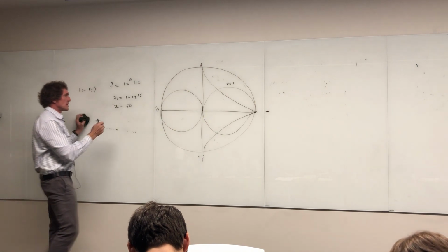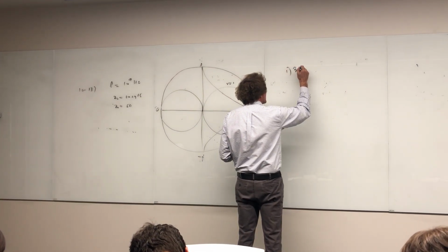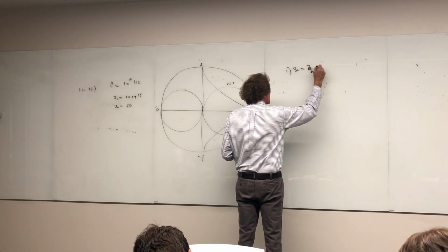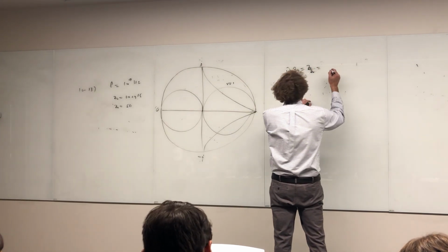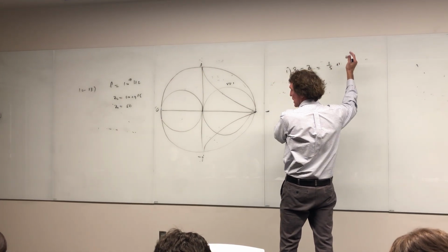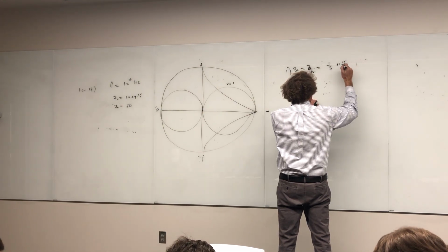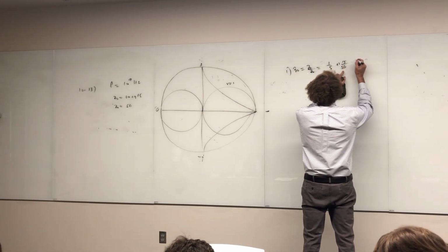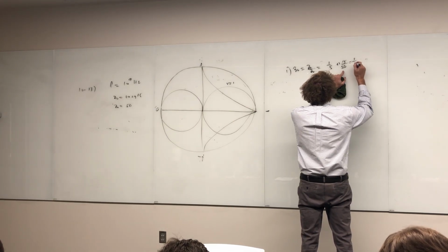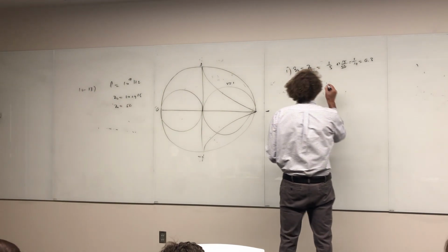Okay, first step, we get the normalized impedance. So zL is capital ZL over Z naught, which is equal to 10 over 50, 0.2, plus j15 over 50, 0.3.